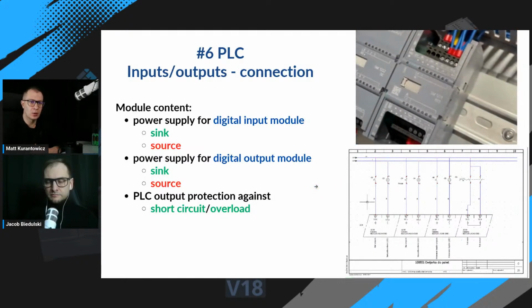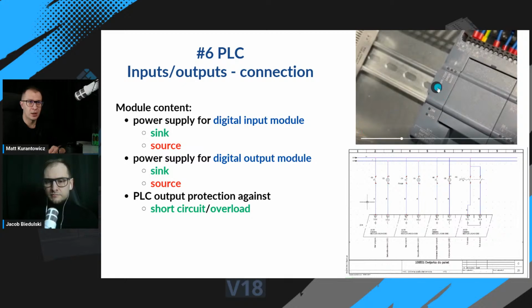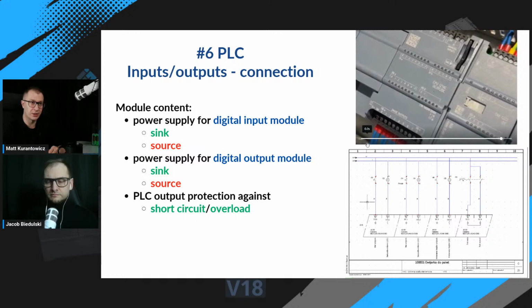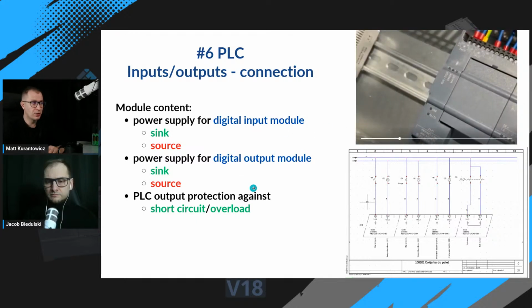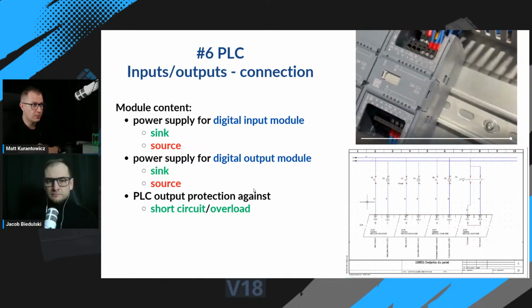In our course, we use, of course, electrical schematic, and also we have a lot of practical videos how it looks like on object on a facility. In this module, you'll learn about digital inputs and outputs, how to use sink and source types of inputs and outputs, and how to protect PLC output against short circuit and overload.